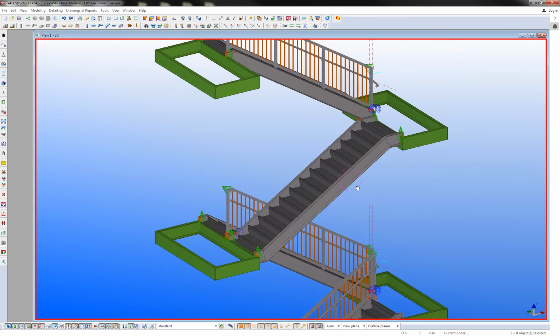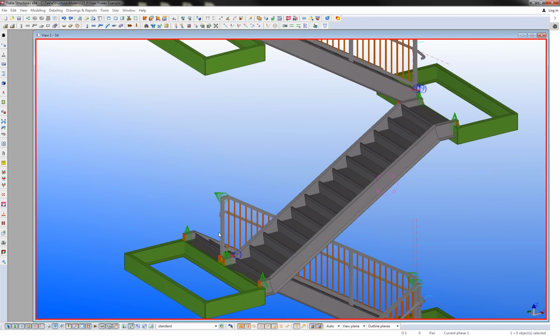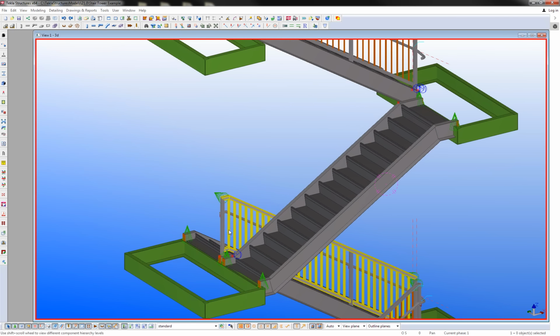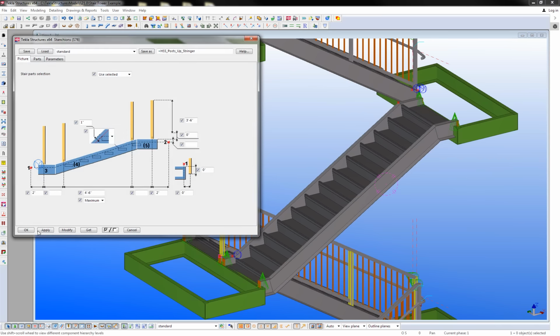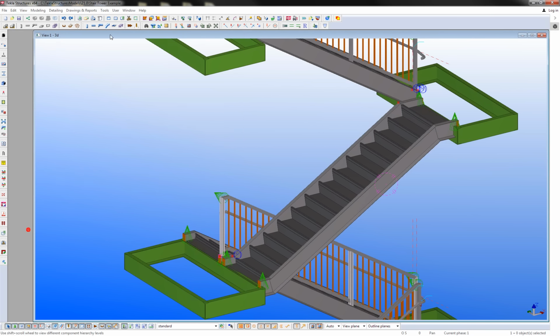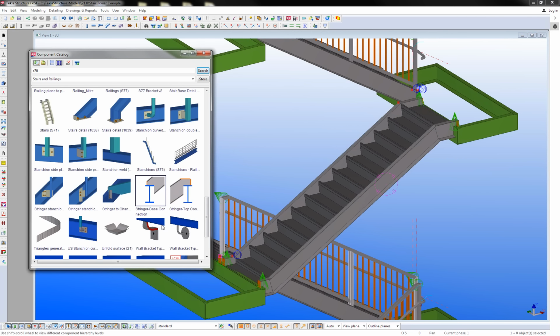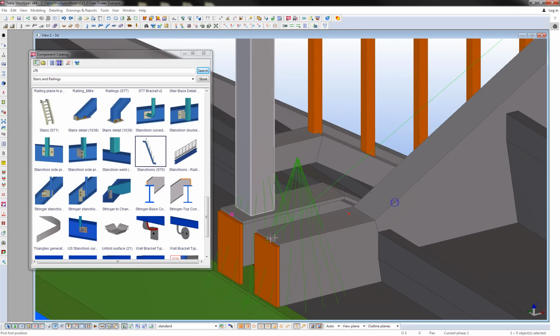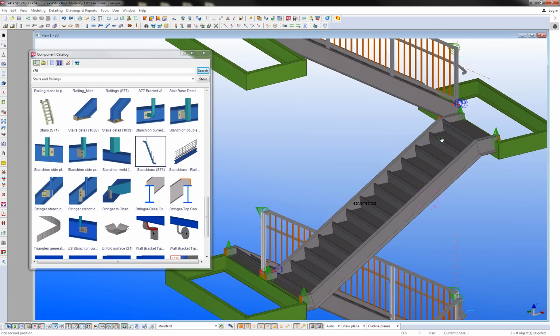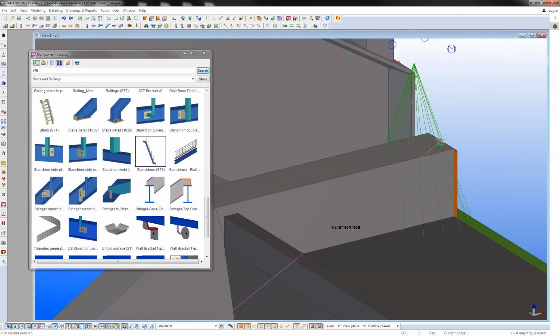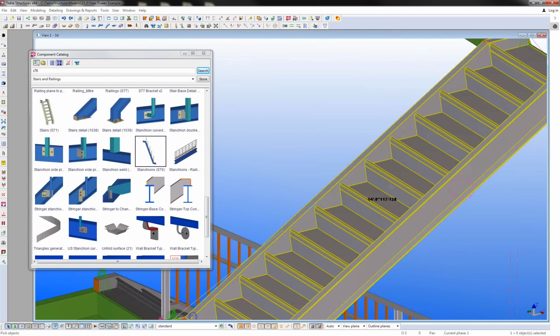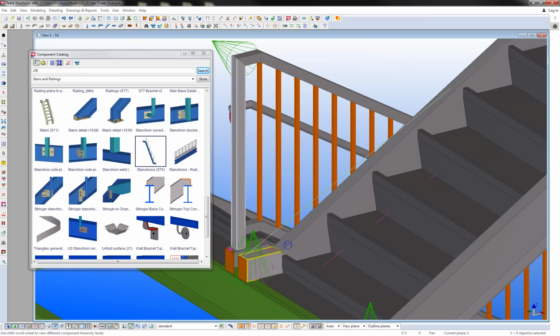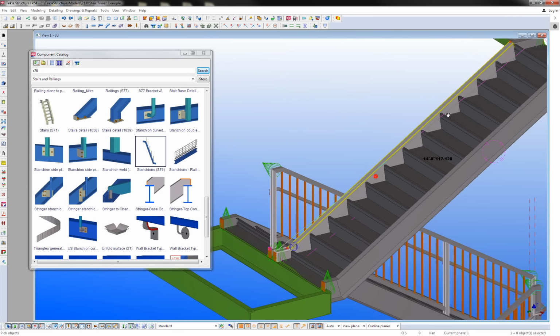So I already know which settings I want to use for those handrail pieces, so I'm just going to put them in just like I put in the others. I'm going to start off with my posts, make sure I set those properties, and that'll be using the S76 stanchions component. Start at the bottom, make sure I end at the top. And again, you want to pick which parts this is going to be bearing on, so that'll be my 3 stringer pieces.